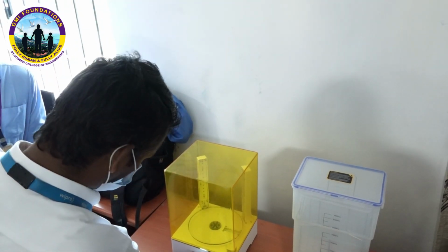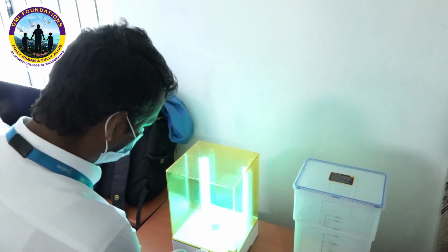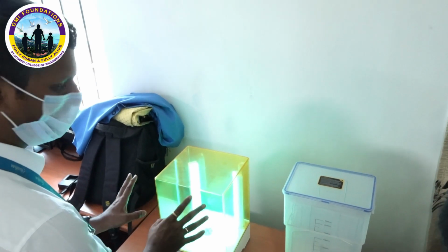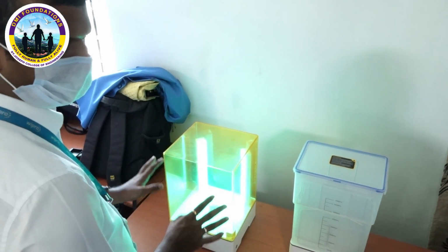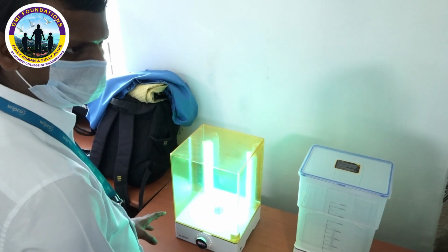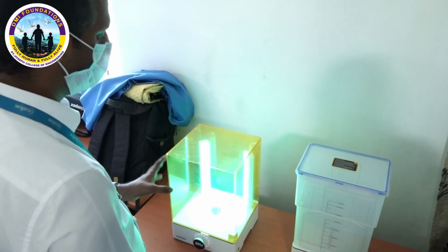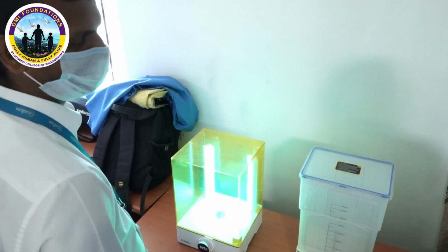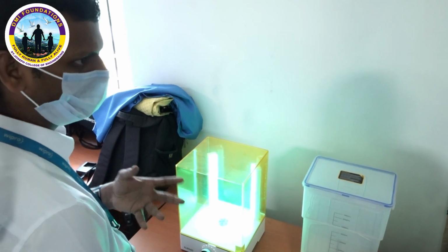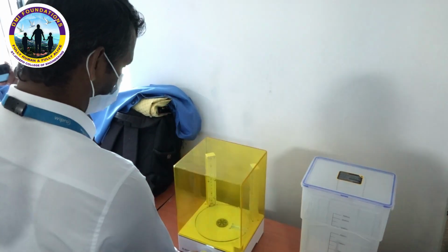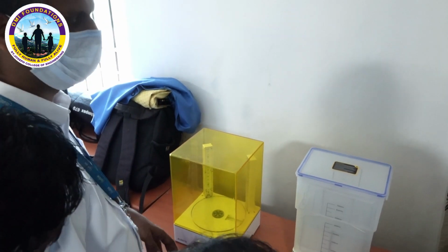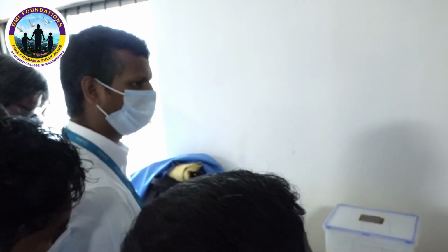Once this is done, here also you can set the time and click it. The UV light will be on, and it will start curing. Here also UV light, here also UV light. But here we are keeping it for a longer period. There it is like 4 or 5 seconds for each layer. That's it. Curing and temperature maintaining? No, nothing like that. Just exposed to the UV light.